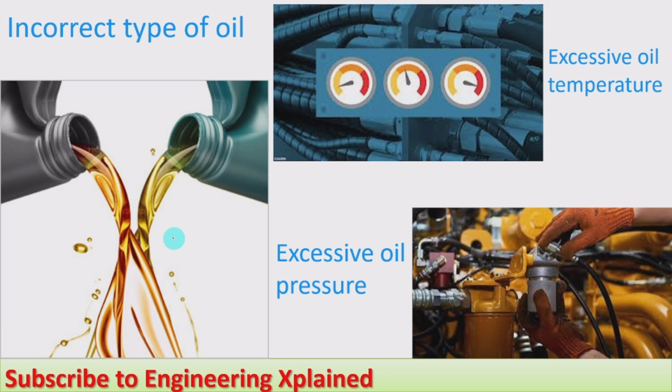For example, the petroleum based oil, synthetic based oil, then some of the chemical oils, then that is manufactured oils. And in the petroleum based oils also there are different grades which are to be used based on the loads or the force we are going to apply, and whatever the system is defined, that type of fluid is to be used in the system.